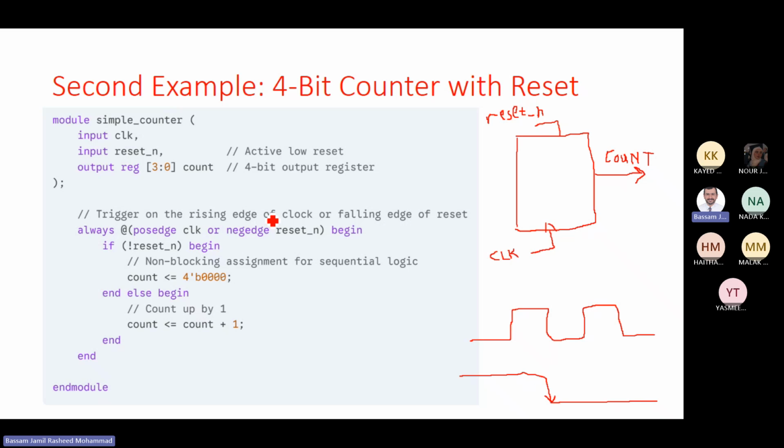When we power up, we use the reset signal. The reset signal. Let me get my laser pointer. The reset signal here informs the hardware that I want you to come up to a known state. Well, known state means what? It means all flip-flops in the design must have values of zeros, roughly.